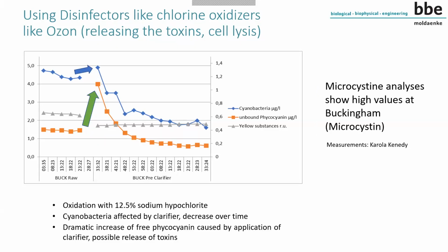And if you measure activity, it takes some time because of the light and laser light and so on. It takes more time. Many people who use online analyzers perform a measurement once per hour. Of course, you can reduce the time, but this is often sufficient to have an overview of the dynamics of the water quality.